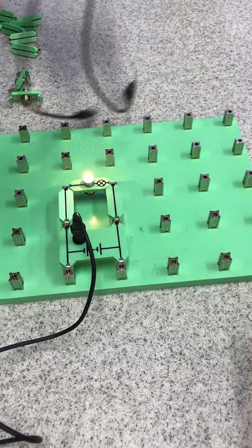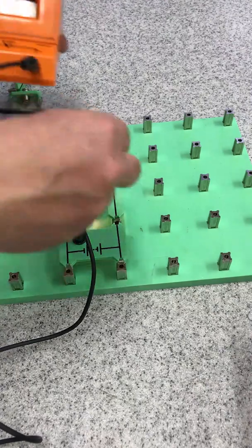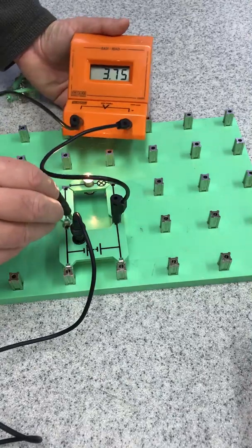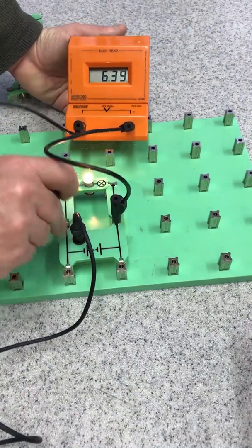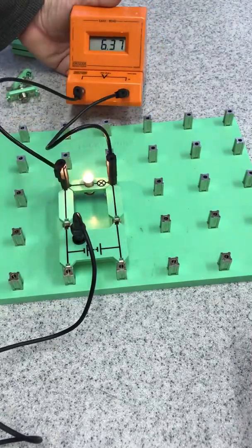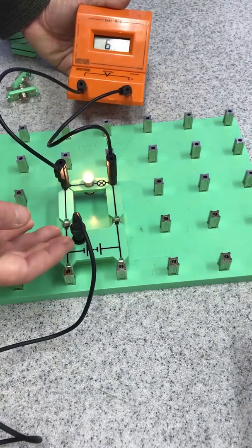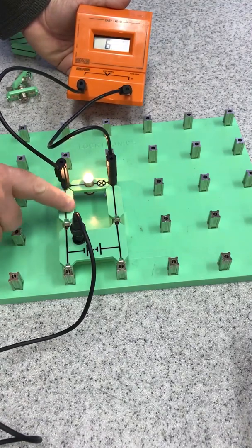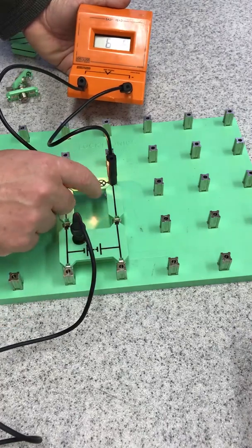So what I'm going to do now is just do the same experiment, but I'm going to investigate a parallel circuit. And obviously with one lamp, that's the same arrangement as a series circuit with just one lamp. So again, 6.4 volts is given out by the power supply, and this lamp is getting 6.4 volts. So all of the energy, the electrons are being given 6.4 joules per coulomb. They're being given 6.4 volts worth of potential energy by the power supply, and that lamp is using that